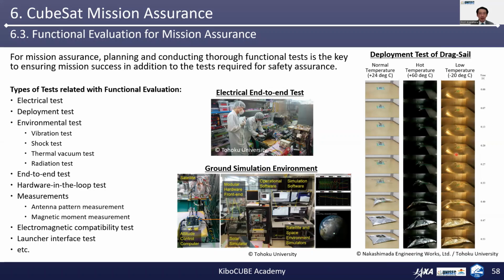And these are deployment tests of thin film deployment mechanism in normal, hot, and cold temperatures on ground. There are no rules about functional testing, so please be creative and conduct sufficient tests in order to ensure the mission success of your CubeSat.